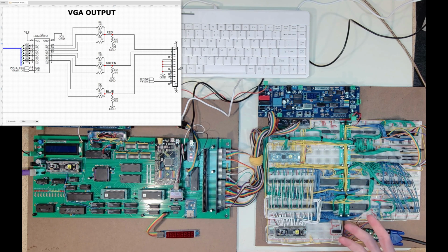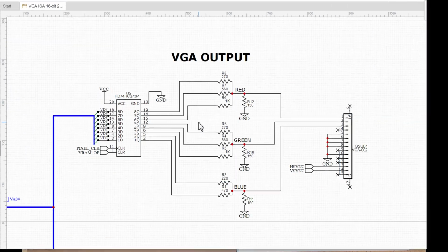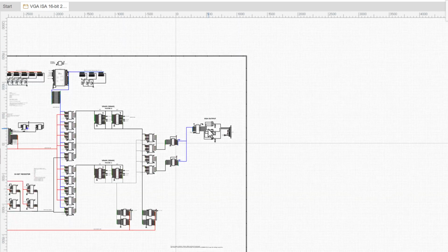So when the system boots up, it's going to initialize, it's going to set this to black, and while it's writing that, it's outputting this frame to the screen, which will be white noise. Then it's going to toggle and output the black to the screen while it fills this in with a solid white, and then it's going to toggle again. But then at that point, as I press F12, I can manually toggle those. And those toggles are happening on VSync, so I do have it tied to VSync, and I'll show you real quick how I did this on the VSync.